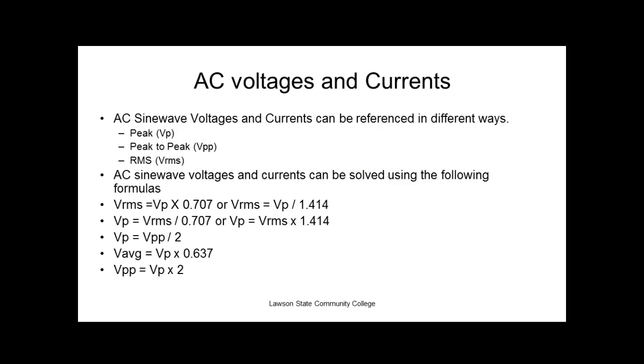So we'll try to do that. I think I got a power cord around here somewhere, and I'll put it on the oscilloscope and let you see. It's about 340 volts peak to peak to get 120 volts worth of work. Now, a lot of people say that's a waste, but what we can do with AC that we can't do with DC is run it through a transformer. And what does a transformer do? Y'all know what it does? Yeah, we can step it up or we can step it down.